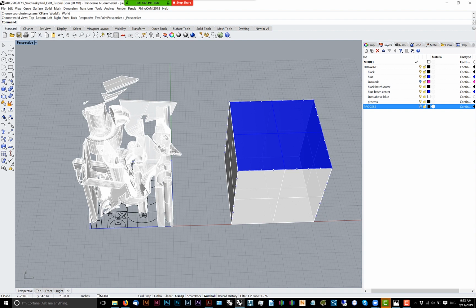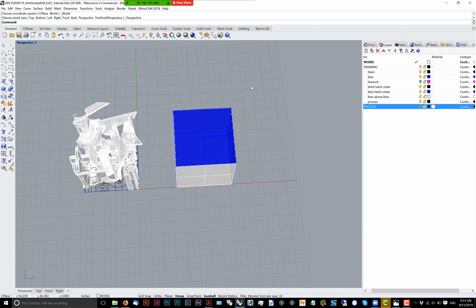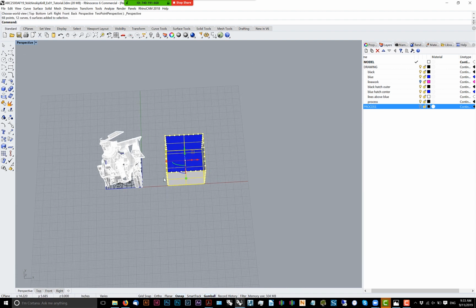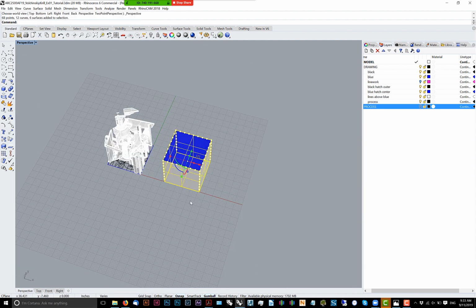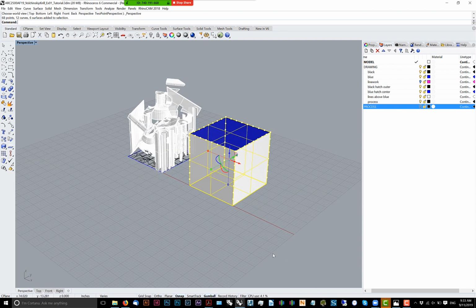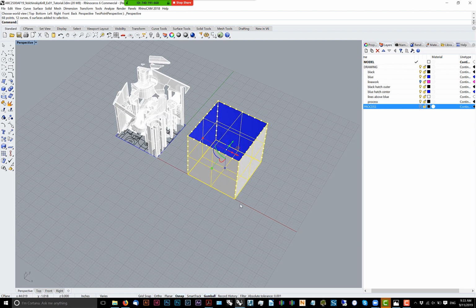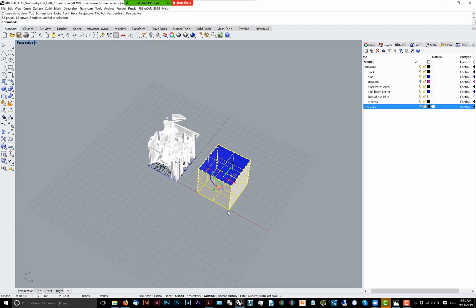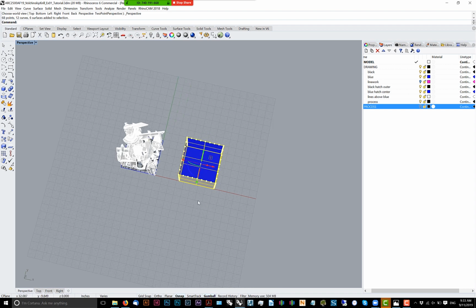Now it's important to choose the axonometric projection technique that you'll be using. I'll demonstrate these techniques on a simple cube, and we'll be using this construction plane, the C plane that you see at the origin, denoted by the Rhino axes, as the projection plane onto which you will be projecting. So I encourage everybody to open up your geometry from your assignment, because at the end of this tutorial, you'll be asked to turn in on Blackboard whatever drawing you create using a similar process.